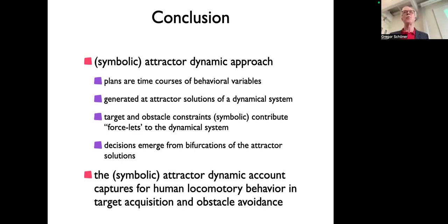And then we're able to use these model equations to predict under which density conditions and velocities and so on this arises. So one of the measures that are taken in a lot of places is to minimize perturbations. These shockwaves arise when there's perturbation. The perturbations are, for instance, cars entering, and here in the Ruhr-Schnellweg, I still use this name, the access ramps have this limitation that only one car at a time can enter. That flowed out of that kind of research.